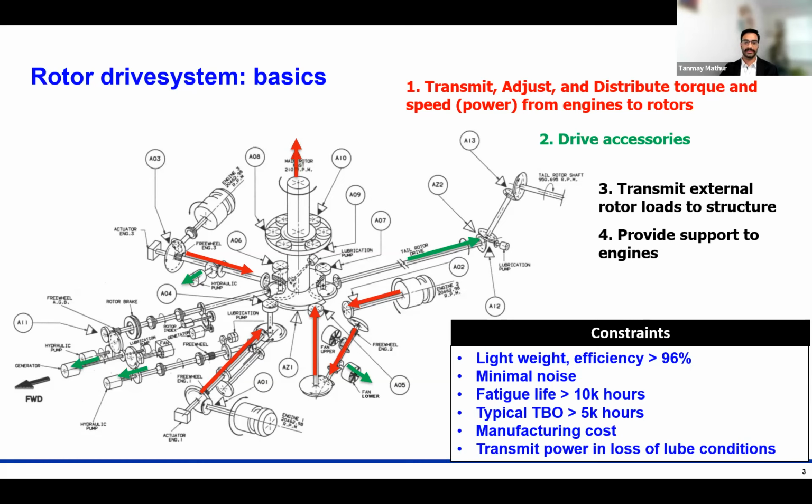So it must be lightweight, shouldn't make a lot of noise in the cabin, must have a very high efficiency, high fatigue life, and time before overhaul, low manufacturing costs, and must also be able to transmit power when you have loss of pressurized lubrication.